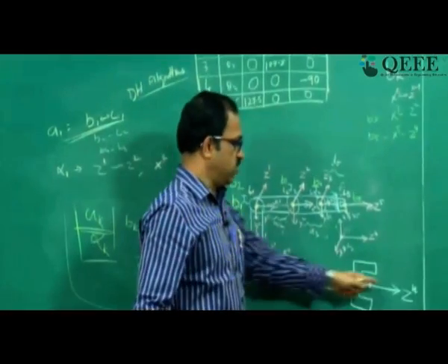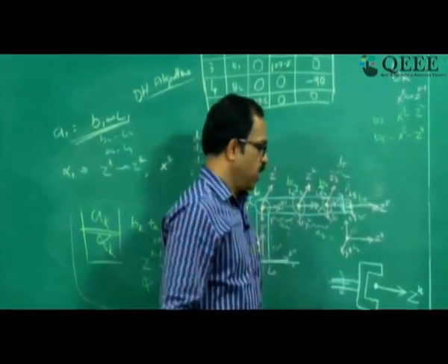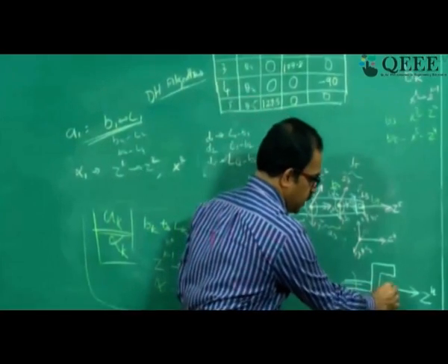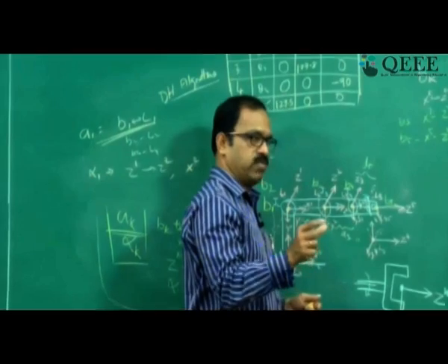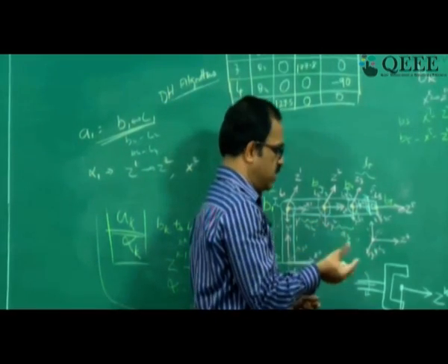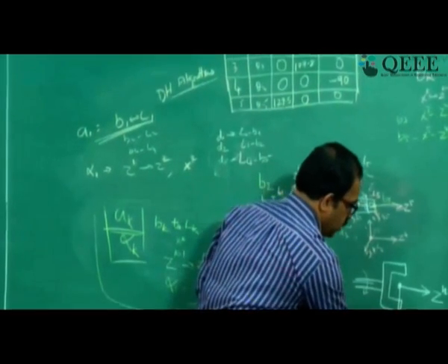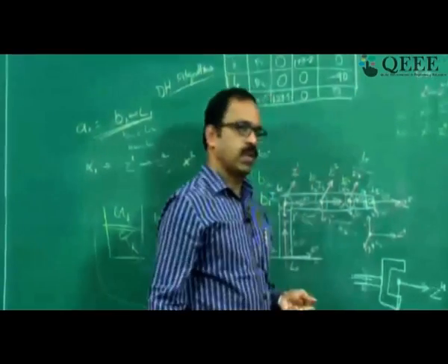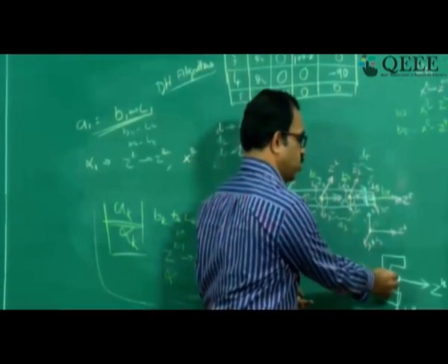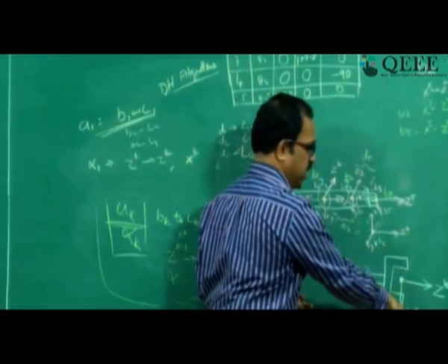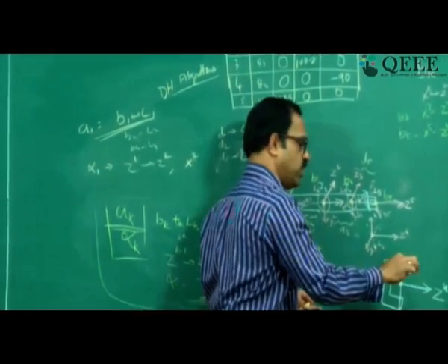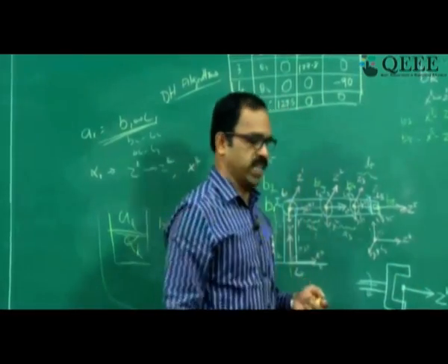Okay, so this is Z axis along the roll axis, and the Y axis is basically assigned along the open close direction of the gripper. Suppose you have a gripper, we assign that as the open close direction, that Y will be in this direction, and Z will be always assigned normal to this. So depending on the way you put Y in this direction or this direction, your X will be this direction or this direction depending on the right hand coordinate frame.